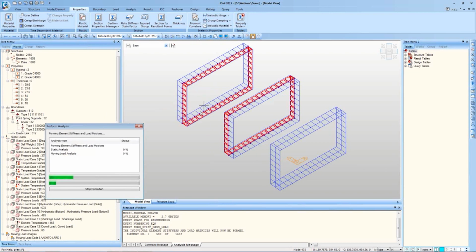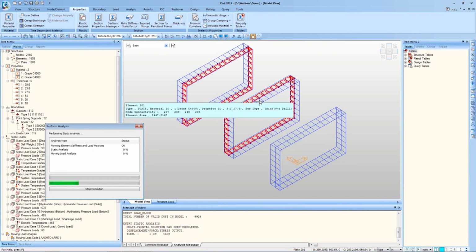And let me explain what I just did. I defined cut planes at 3 positions and defined 2 beams between the 3 sections. And now when I'll be checking the results at resultant force diagram, the results are displayed for virtual beams at both the ends of the beam. So results will be displayed at I end and J end of the first beam and I end and J end of the second beam.